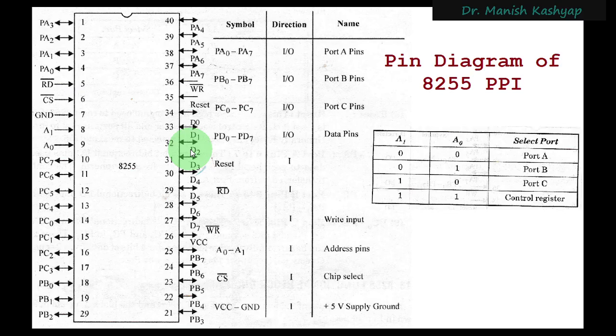Because you can use an 8-bit register and transfer 8-bit data into that. An example could be MOV AH, 55H. So those commands were there. So half of the data bus of 8086 can be used and connected here for dealing with the 8255 programmable peripheral interface, right?